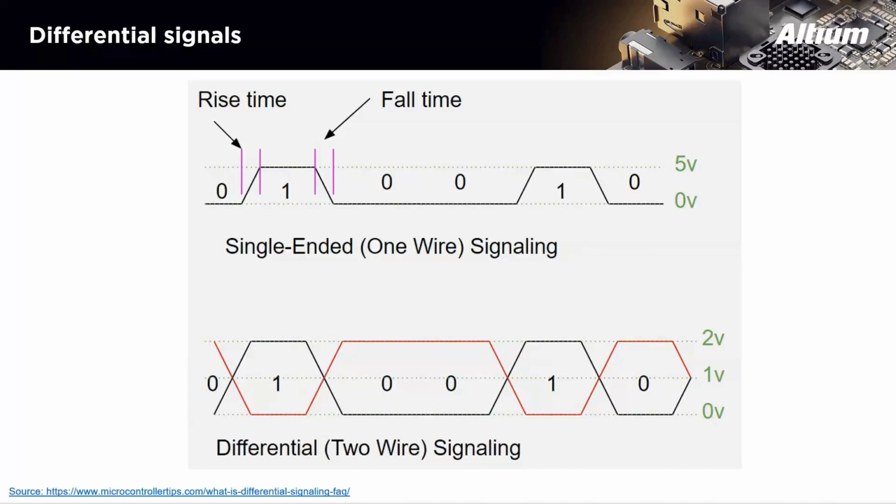As you see in the picture from Microchip, you can see these are live traces. This is how a single-ended signal looks, whereas in differential pair signals both are of the same voltage levels but opposite polarity. The receiver will observe the voltage difference to extract the right data. Because of these opposite polarities, the noise will get eliminated. That is why these differential signals are used in high-speed signals, for example USB 2.0 or HDMI signals.